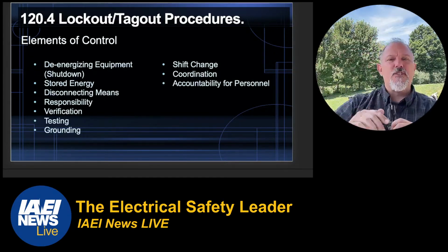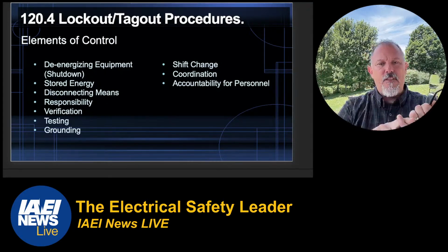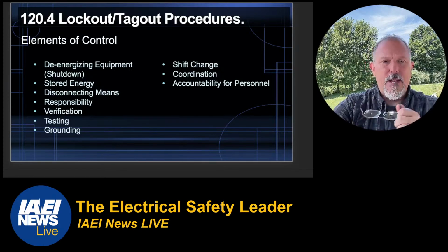All of the elements of control have to be in place. It's not just lock and tag out. You have to verify. You have to de-energize the equipment. You have to release all stored energy. And I want to touch on stored energy.